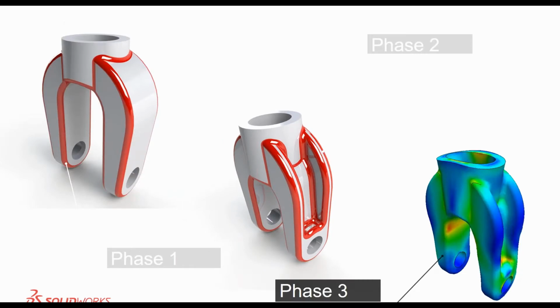Phase 3 is to perform a simple simulation on the part, get some results. Usually a factor of safety is the final answer, which will be used to determine if you've done the modeling correctly. The simulation portion is very quick, and usually utilizing Simulation Express for this is the best option due to the simplicity.